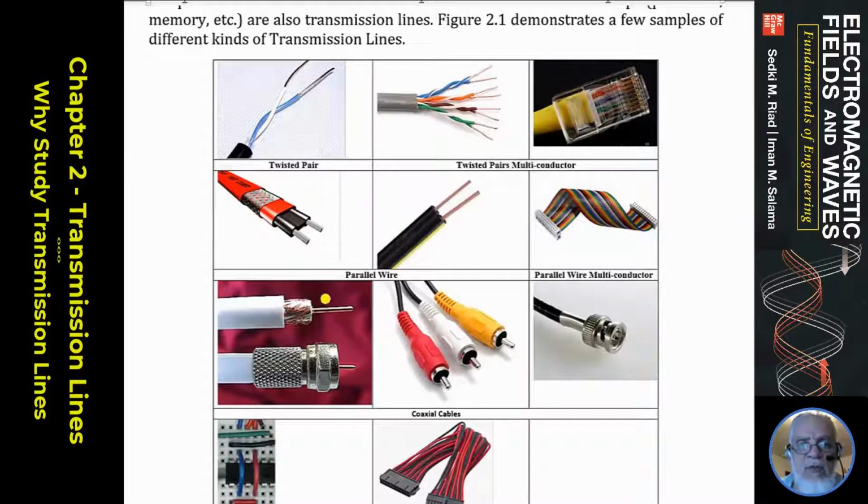Here's another arrangement where you have what we call a coaxial. Now this is a cylindrical conductor, and there's another outside cylindrical conductor in the form of the shield, and a jacket that covers all that. That is typically the kind of transmission line that goes into television equipment. So this is the familiar, famous F connector in the TV industry.